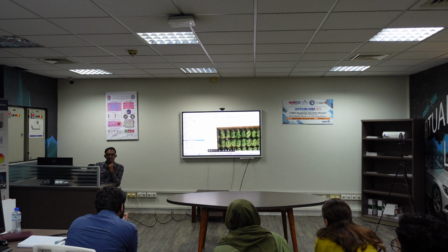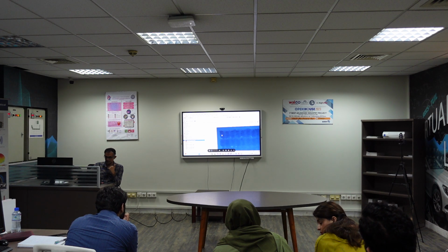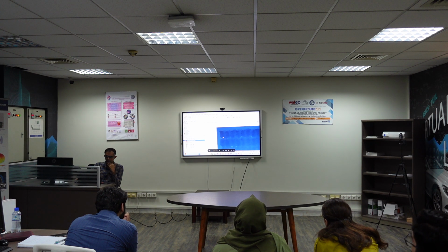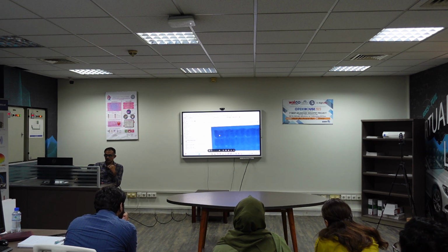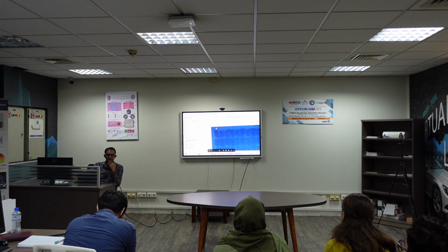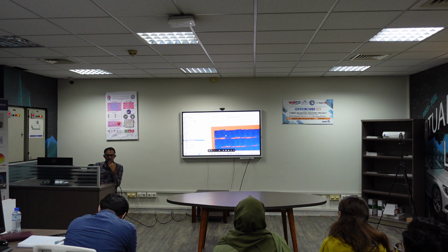However, once this digital surface model is constructed, it has certain errors. It is basically a spilled version of that. It is basically diffusing. So we don't want to sample this point because there is no soil there. It is already somewhat error prone. We want to ensure that the points we are sampling are soil points in the digital surface model as well. So that's how your soil mask would be very important. You have to generate a very accurate soil mask if you want to sample this or interpolate your digital surface.